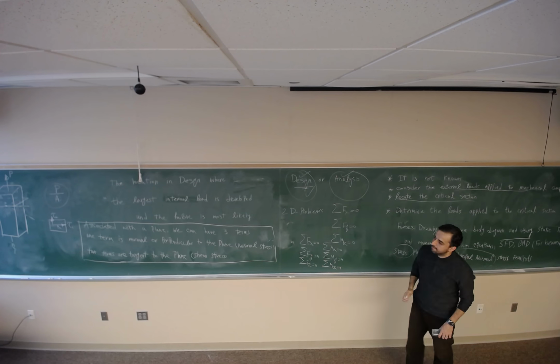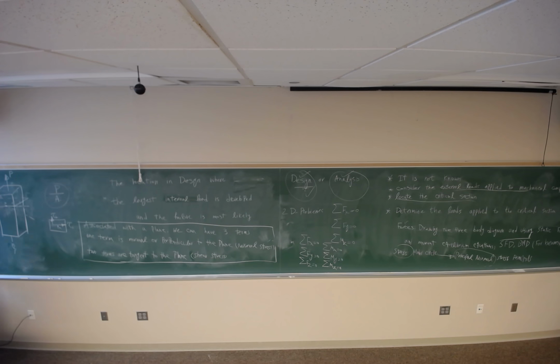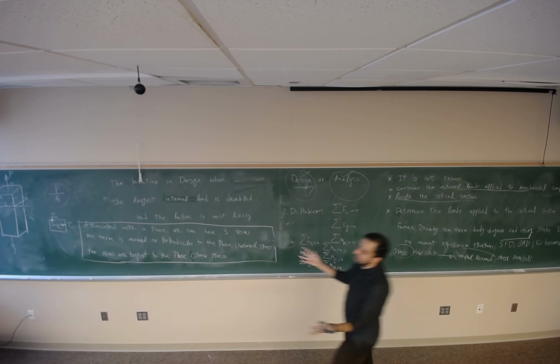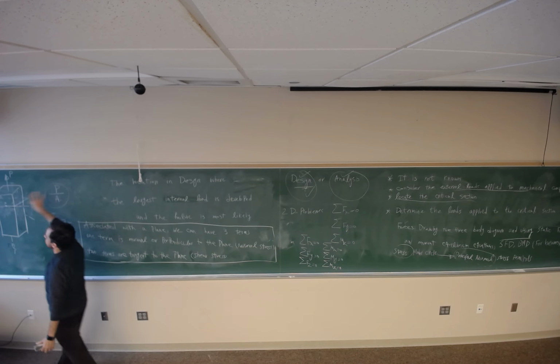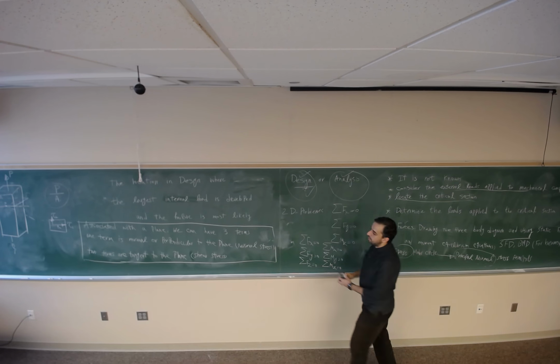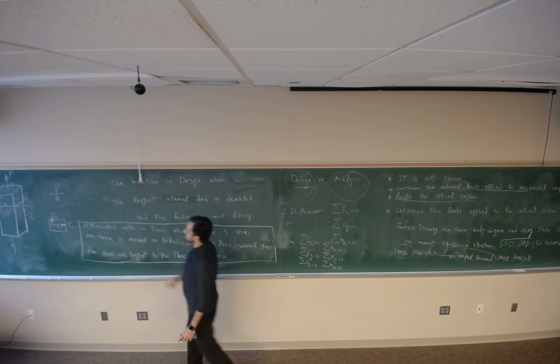Again, we started with the stress at the point. We learned that due to the definition of the stress, we should specify which plane we are talking about, and we have infinite planes passing through point A, so we can have infinite stress terms defined, but at the specific plane that I have here, I can define three terms of the stress.